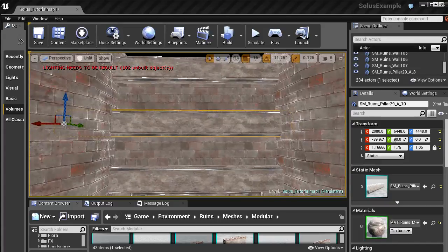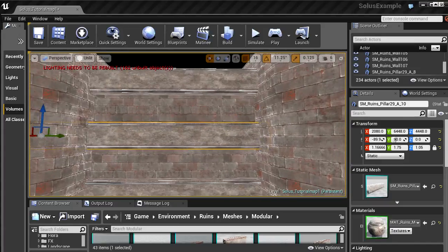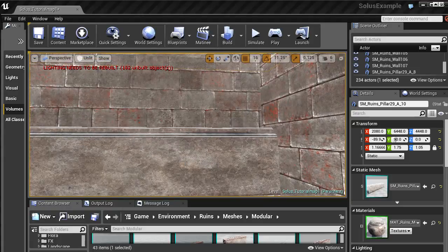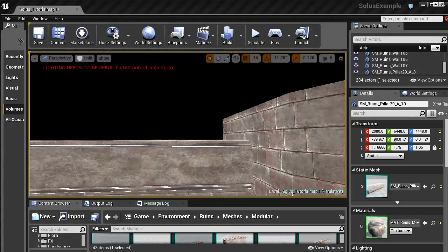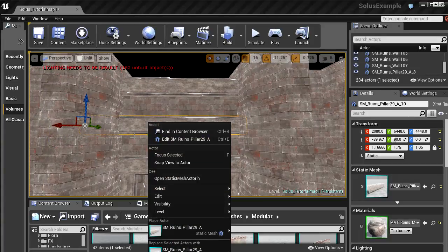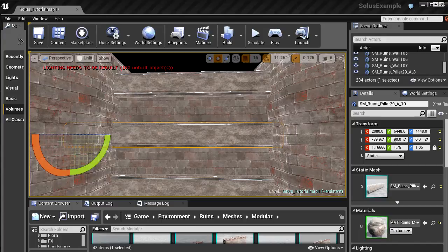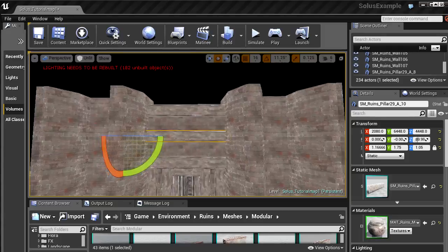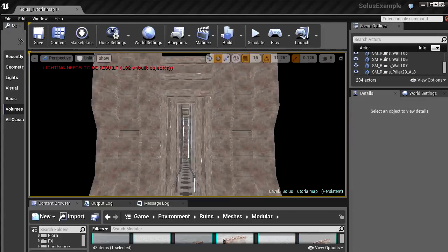Also, just some random notes. If you're gonna copy paste pillars like this or bars or whatever, you can see that the texture repeats. For example, this pattern here, same. So then you can see it's just a copy. So what I tend to do in these kind of cases is mirror or rotate one of the pieces or all of the pieces. For example, I can rotate it, and you can see the other side has that strange part on the left. So it's a bit more random, so you get a bit more variation.